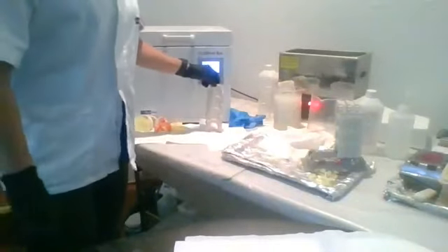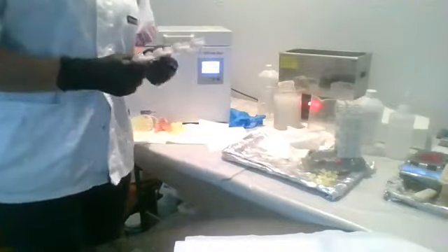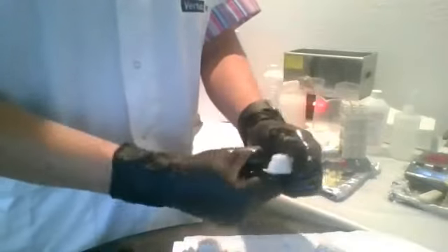Okay, so now you can break these off before or after you put them in the cure oven. I choose to do mine after because then it's a nice clean break. And you can take out the lattice. I find that it looks nice and it looks fine, but these just snap right off. You can see there's no scarring from my supports. You can just pop these little guys right off on the sides because they're all perforated, basically. You actually use less material than you would if you're doing this in single level with all the other supports. You have less support material altogether and you have a faster build. Okay, so now you're ready to go in and do your thermoforming. If you don't like your lattice, you can also take that off as well.